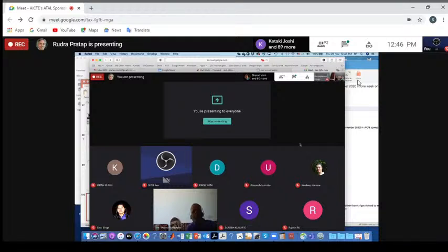However, MEMS technology is good for building transducers, right? That's where it has its strength. So what we can do for you is we can build transducers which will monitor your coating, right? For example, I can have these very, very tiny ultrasound transducers that can keep monitoring the thickness of the coating on the tool, right?